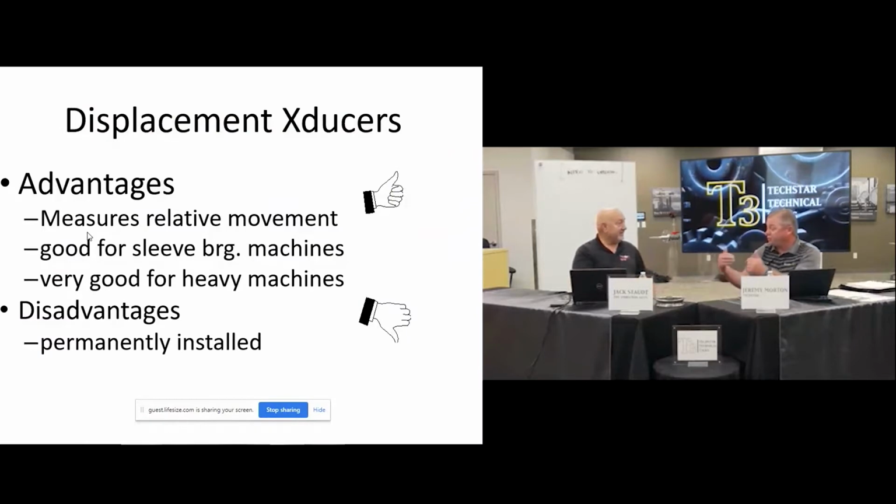So it's a much more intrusive installation. Yes. Typically you have to drill and tap into the bearing caps and through the housings if your machine isn't already modified. And that's some of your background, isn't it? Absolutely. That's where we come from. We do that daily. But it has to be the right application for that sensor. Absolutely. You've got to look at the cost impact of that machine going down and justify whether it's worth the expense of putting a system like that in.